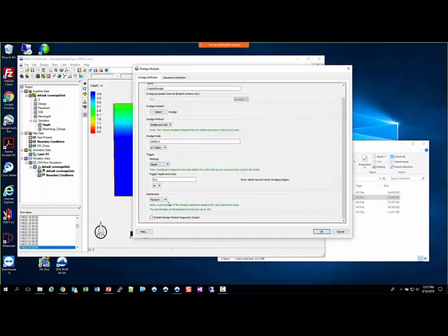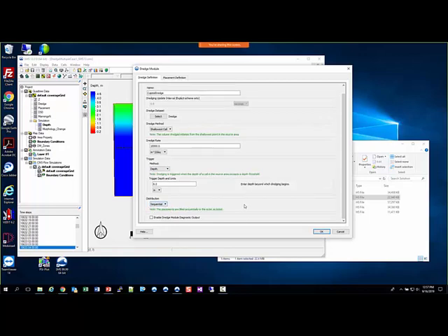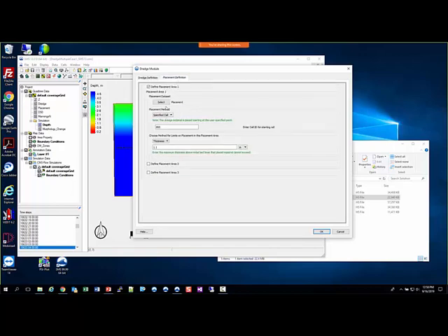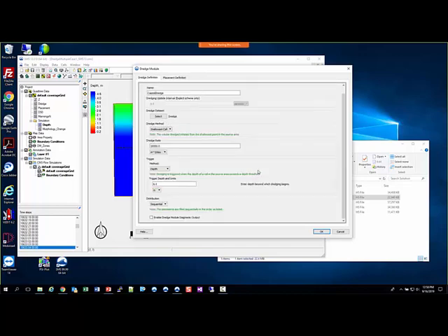Same thing for the distribution. As I mentioned, there's percent that we showed, but there's also sequential. And so what that does is, instead of a certain amount for all the different placement areas, it starts in the first placement area and fills that to capacity. And if there's anything left over, then it moves to the second. And then if there's anything left over, it moves to the third. So that's one option that you can tell it to choose, okay, not just everywhere, but in order as needed, based on the amount of material you are moving from a certain location.